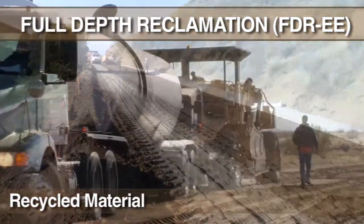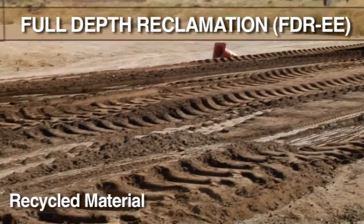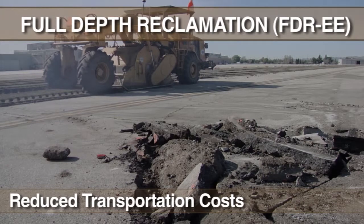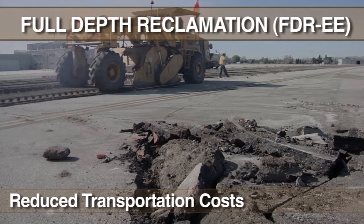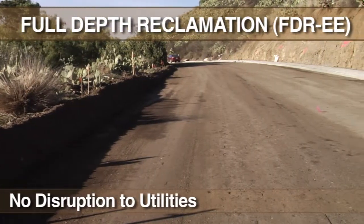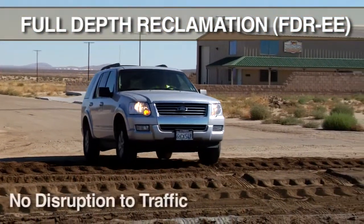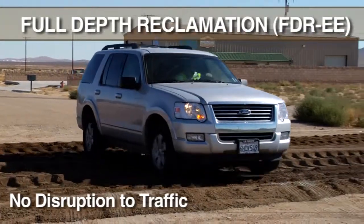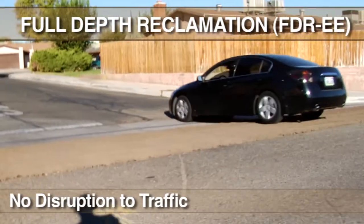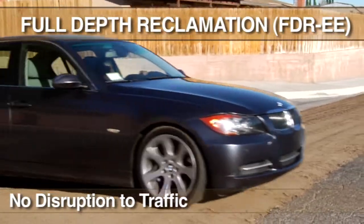A 25-ton truckload of engineered emulsion can, on average, eliminate the need to remove and import up to 60 dump truckloads of material. Transportation costs are reduced, since the existing roadbed is recycled in place and not hauled in and out of the job site. Utilities are typically not affected, since the FDR process is done in the confines of the existing roadway section. The traveling public suffers little disruption since the pulverized material remains in place and does not create a long-term lane closure. The stabilized materials can then be opened to cross-traffic in less than 1 hour versus days with typical reconstruction.